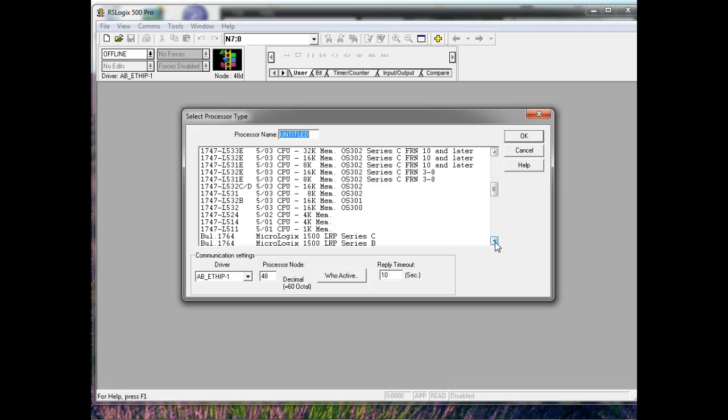Well, we're not in the file number right now. We're selecting the CPU. On the modular PLCs, it's usually in the door. You open up the door, and then there's a label on there that gives you the CPU. On your fixed PLCs or your hybrid PLCs, it's going to be on the side. Okay, so here there's a label. Most of the time it's actually silk screened and painted onto the side. That's a really good question. So on this guy, where's it going to be at? Yeah, you look at the CPU and it's down at the bottom.